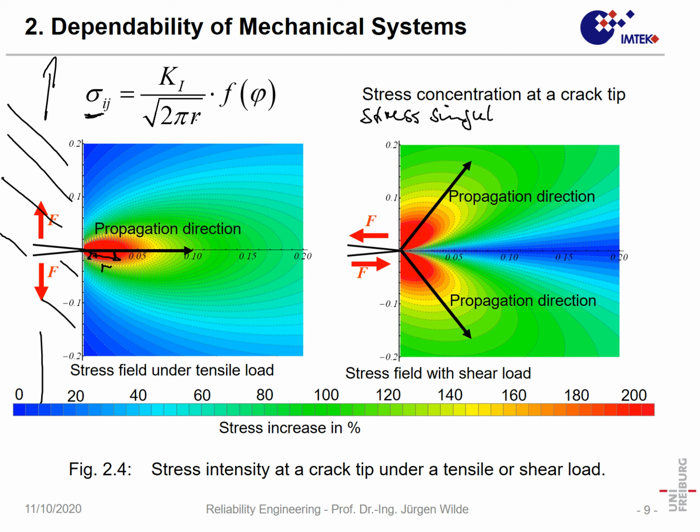The leaves will not even slide against each other if you just press in a perpendicular way, but you can easily take apart these leaves, and that means the energy you need in tension is much lower when you want to separate this, contrary to when you press on it. And also it is a good idea to keep in mind that a brittle material typically has a low energy of fracture.